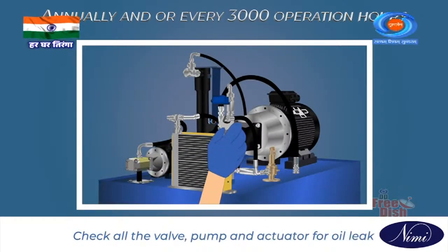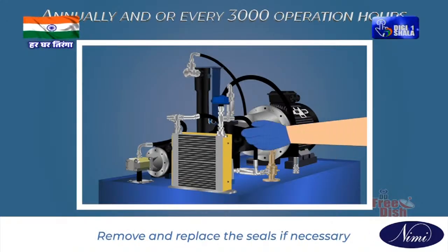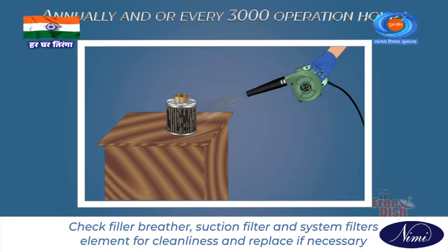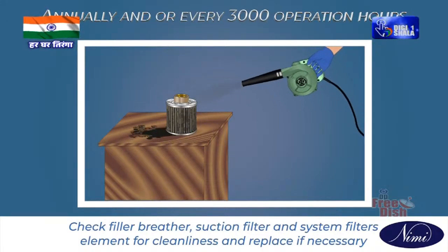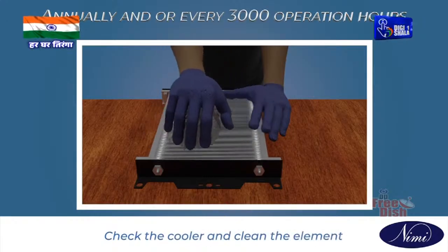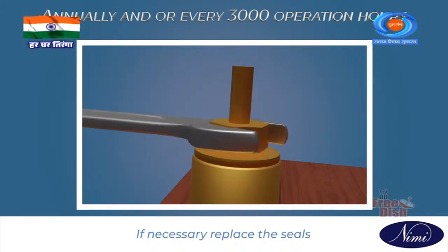Check all the valves, pumps and actuators for oil leaks. Remove and replace the seals if necessary. Check the filler breather, suction filter and system filter elements for cleanliness and replace if necessary. Check the cooler and clean the elements. If necessary, replace the seals.